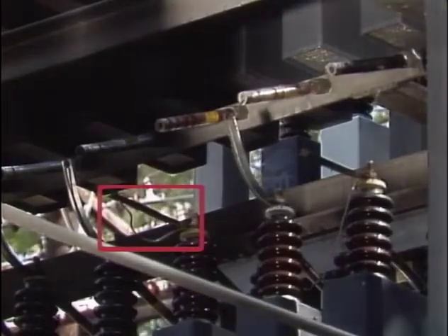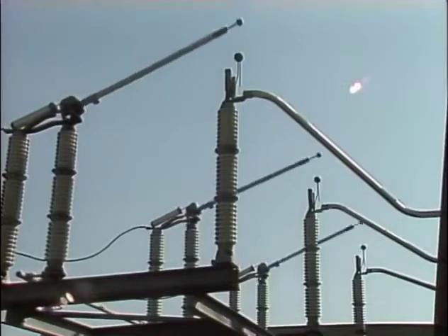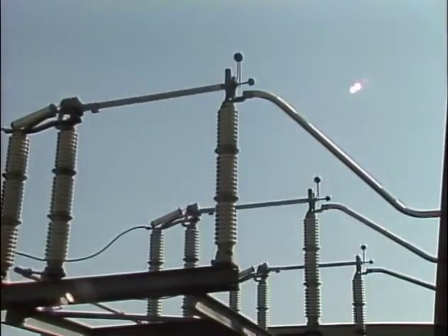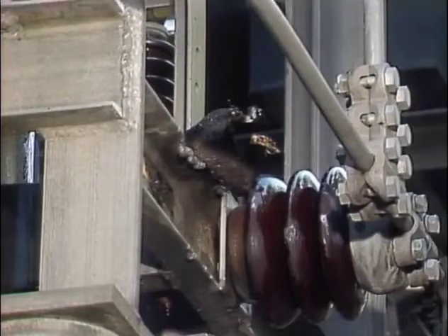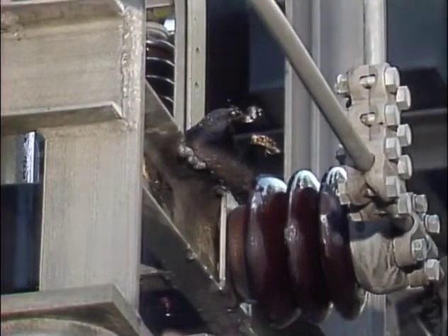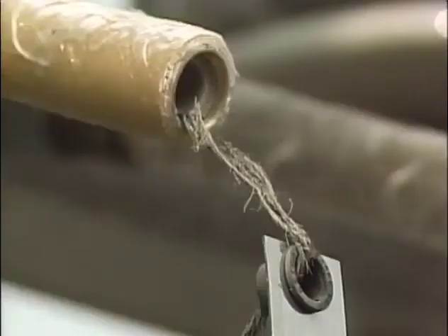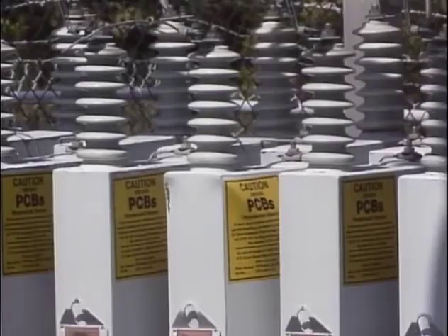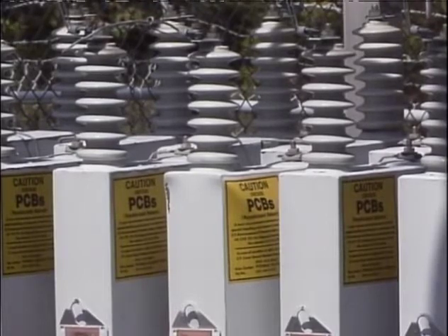Capacitor fuses can blow for any number of reasons. For example, fuses can be blown by excessive current from switching. Another cause of blown fuses is animals such as squirrels, birds, or snakes getting into the bank and short-circuiting a capacitor. Sometimes a fuse blows because the fuse link was weakened by fraying. And there's always the possibility that a blown fuse is caused by a capacitor that failed.